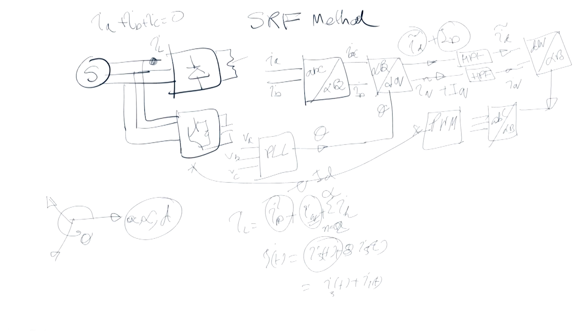For the sake of time, I do not want to go into a detailed discussion of the SRF method, and it has many variants. If it is unbalanced, then we have to add a negative sequence to it.